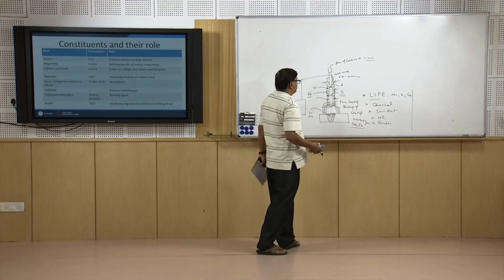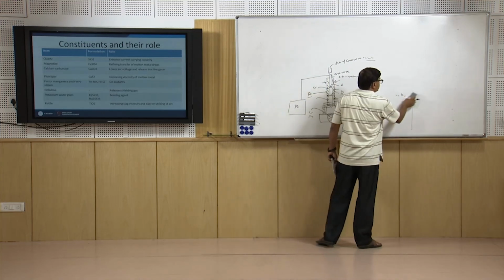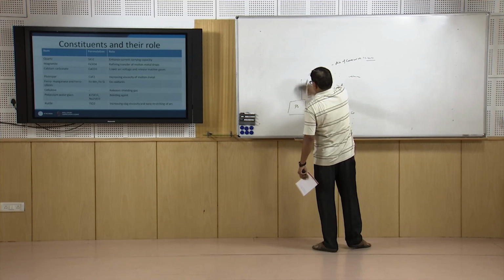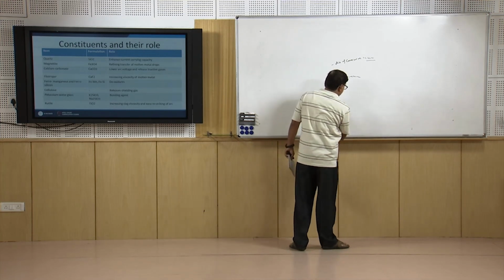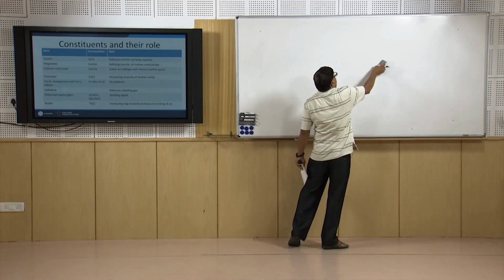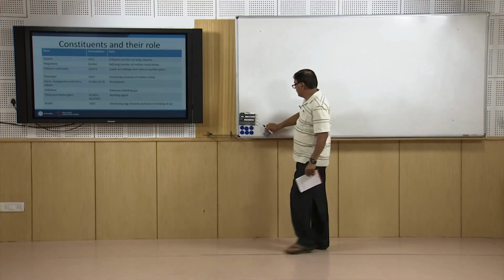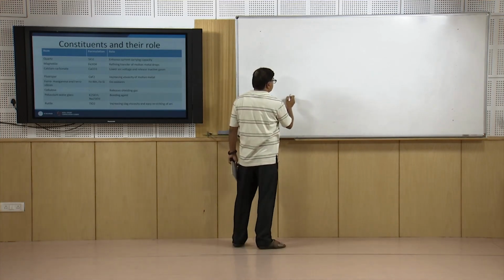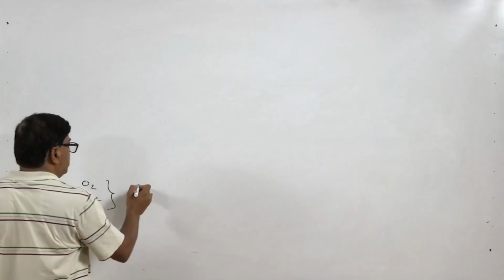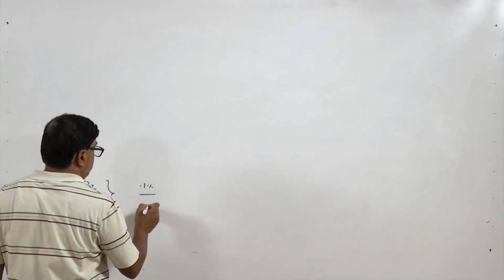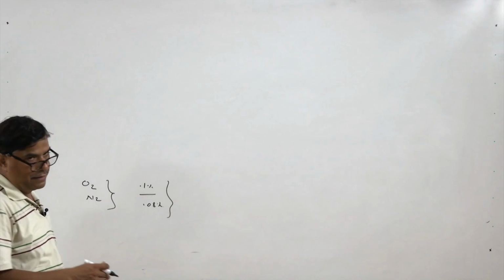So, this is a very important role of providing the coating in the shielded metal arc welding process. The protection provided in this process is not very good, because it forms a very loose cover. So, there is every possibility that the atmospheric gases will interact with the weld metal during shielded metal arc welding, and that is why usually the concentration of oxygen and nitrogen in the weld is on the higher side, normally found at around 0.1% to 0.08%. The higher concentration of oxygen and nitrogen in the weld metal tends to degrade